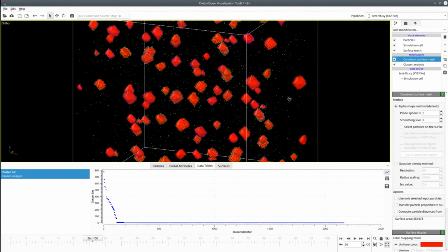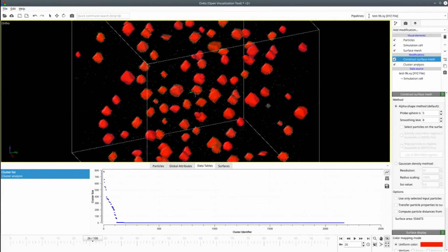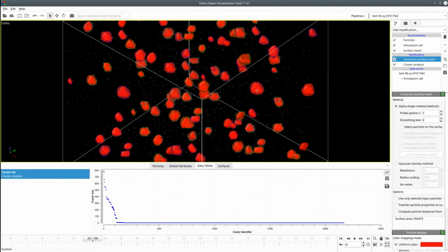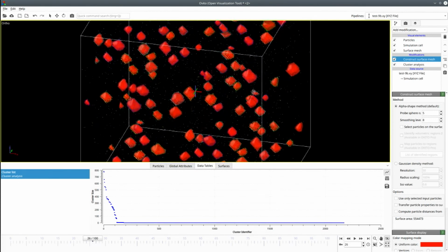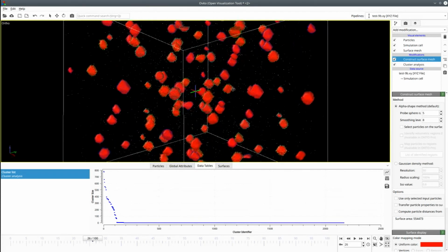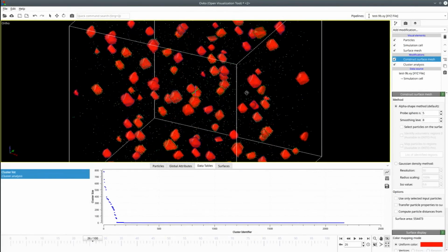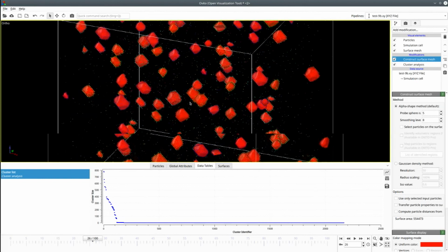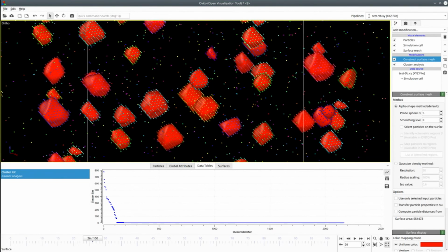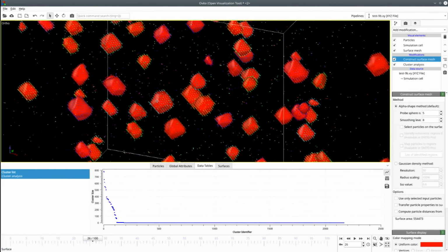And now you see that these particles are somewhat rounded, plus the vicinity around them, B atoms close to the clusters or so, I don't know. This might be helpful. Oh, here's a nice one. You see this one? It's nicely faceted. This one here. It gives the impression that the 1-1-1 surface or interface is the lowest energy, so probably it's a kind of equilibrium shape we obtain here.